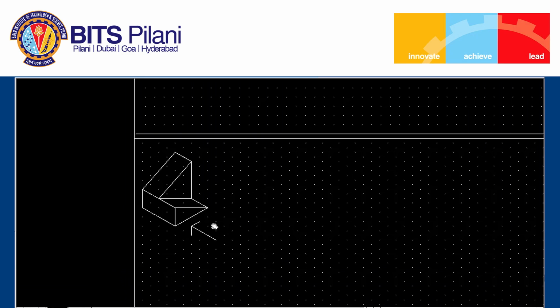First step, find the dimensions for the front view, top view and side view, that is length, height and depth. The length dimension, which is seen in the front view, is across the direction of the arrow. So this is the length of the object. Height is a vertical dimension and depth is the dimension along the arrow. In the front view we can see the length as well as the height of the object. In the top view we can see the length and depth. In the side view we can see the depth and the height of the object.